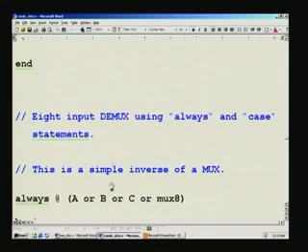Now, what we are doing here is we have got, using the 8-input mux, one output. That output will feed another demux. It is a reverse process, and we see whether what we started with as inputs for the mux appears at the output or not. That will be easy to check while doing the simulation. That is why I fed it back like this.